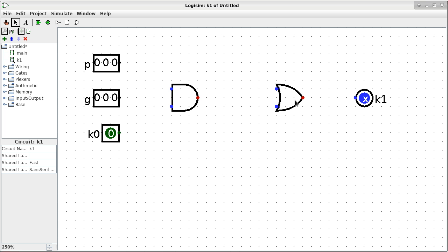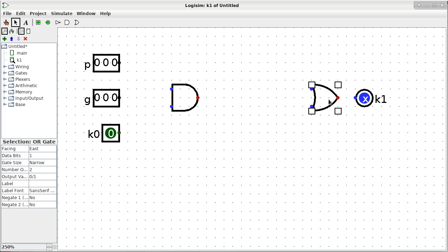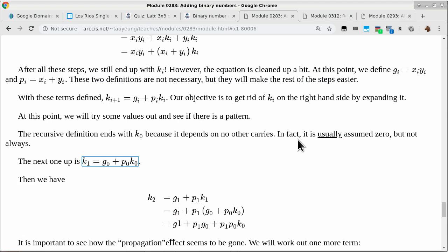Yes. So we know the result is basically the bit OR of something, so that can go straight to here. No problem. But when you look at the equation, I don't need the entire G because I only need 1 bit out of the G, because the input pin has G0, G1, and G2. I only need G0. So I need a splitter to get just G0 out. And the same thing applies to P0 because the input pin P has all 3 bits, and I just want one of them. So I need a splitter for that purpose as well.